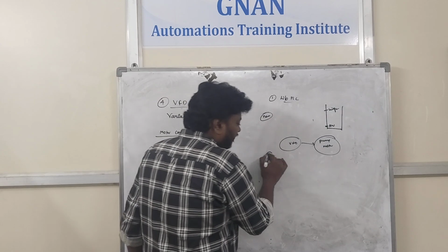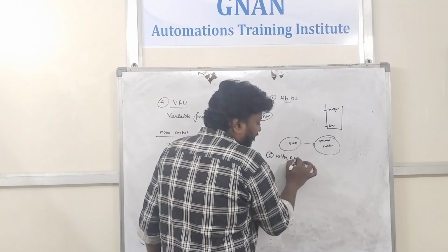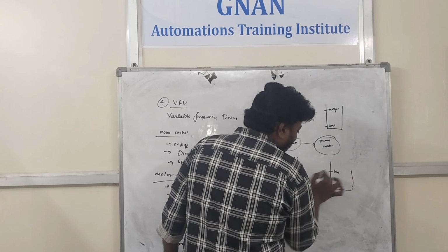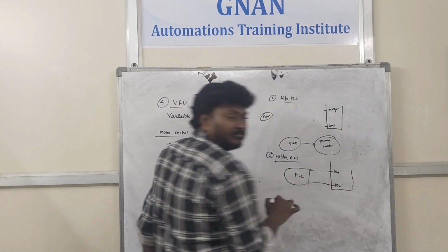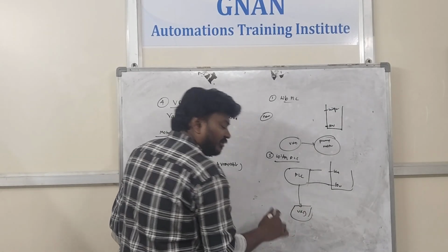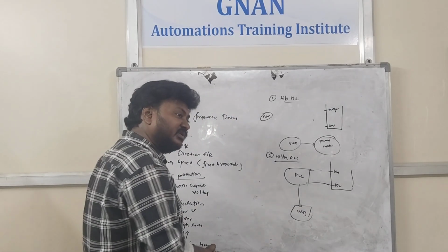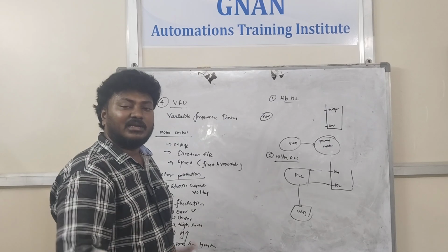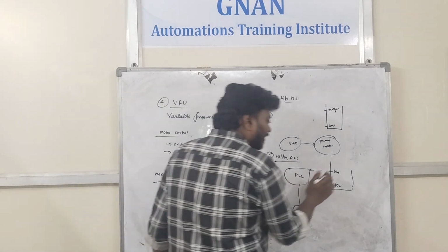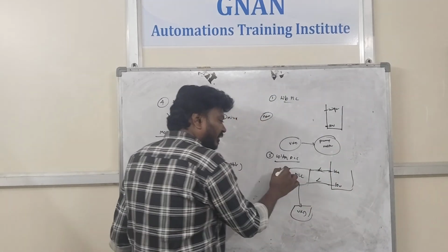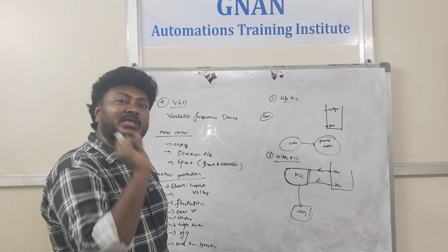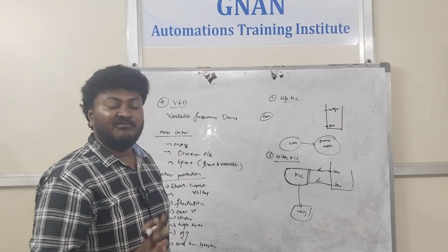But sir, what is the use of VFD with PLC? With PLC, let's say this is low level, high level, everything, PLC is going to take over. PLC is going to give the signal to the VFD: when it should run in forward, when it should run in reverse, when it should run at a particular speed or level, whatever the low level, high level, everything. Every signal PLC can take over. As a programmer, you need to write the program of PLC, VFD, and also HMI and SCADA.